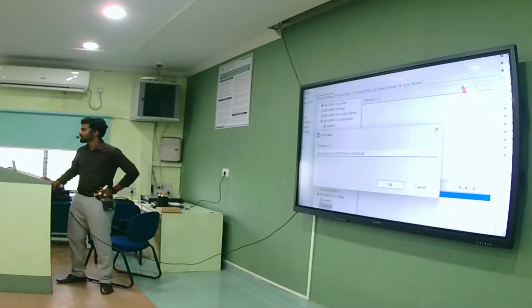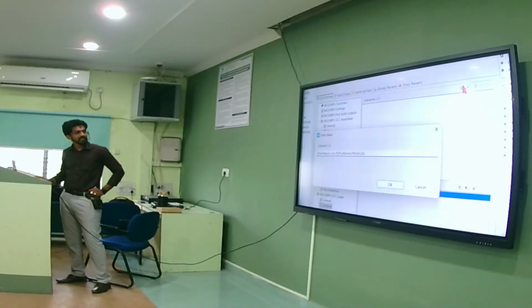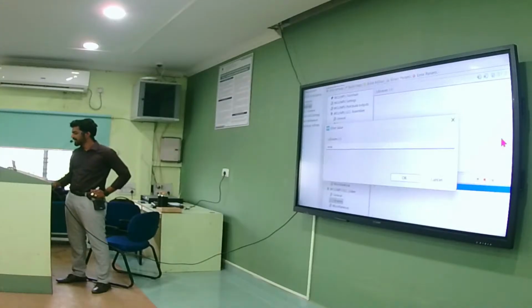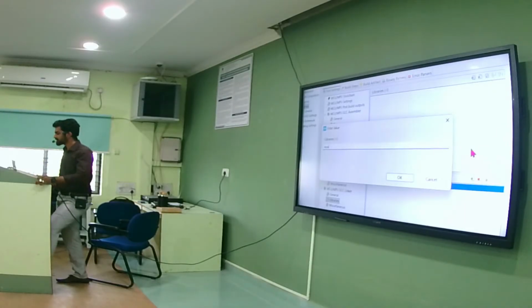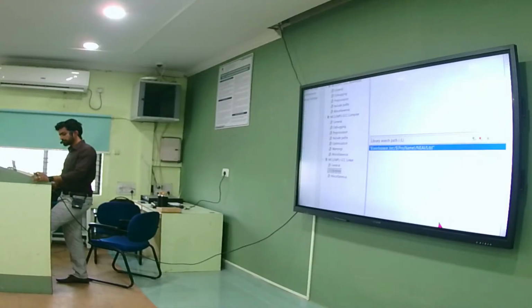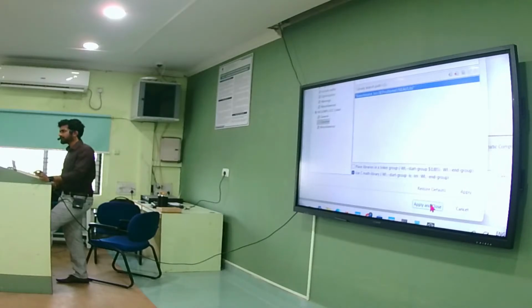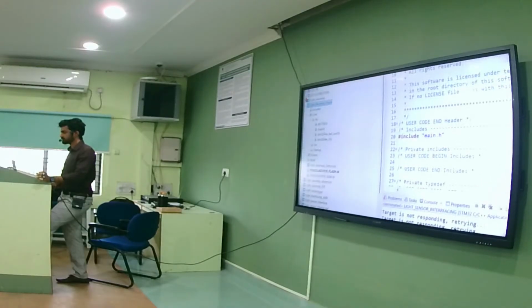See, what's our library name? libneai.a. Is that lib silent? It's a folder name, lib is silent. Then just type there in small letters, neai. It's the library name. lib is silent, neai in small letters. You just type there. Click on OK. Click on OK. Then apply and close. Is that okay?